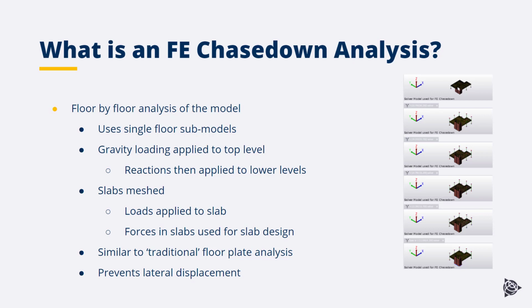As the slabs will not be able to displace laterally, the design moments in the slabs will be for the gravity forces only, meaning our slabs will not be designed to resist lateral forces, and the forces will be similar to the traditional floor plate analysis method.